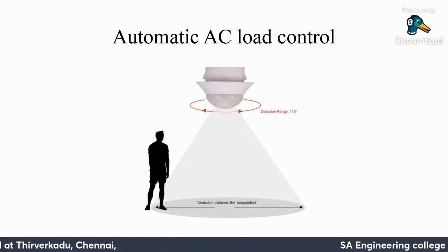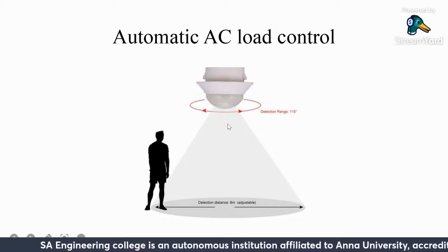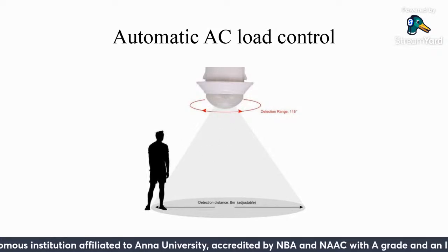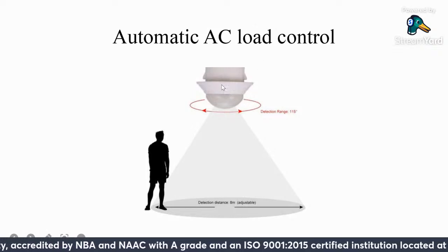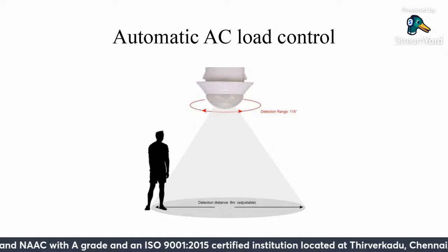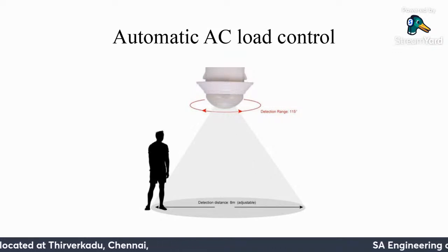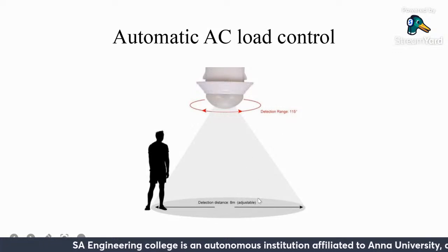IoT system. And here you can see the PIR sensor, but in our project I'm using an ultrasonic sensor which detects the human presence, and after that it will trigger the NodeMCU microcontroller, and it will process the data, and we can control the load accordingly, as we programmed or as we planned. Here we are controlling the load according to a range of 105 degrees, and a distance of 8 meters in the horizontal direction.